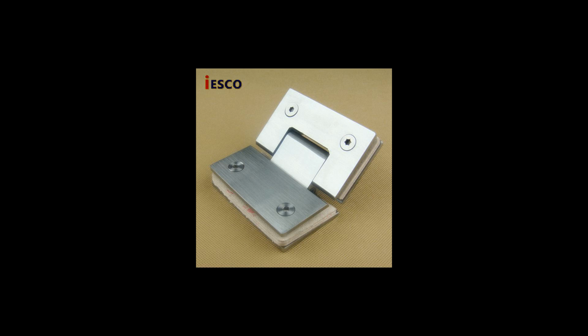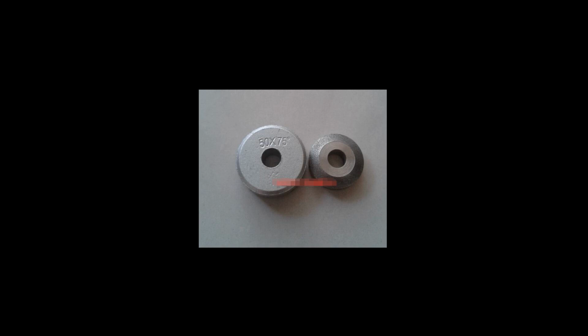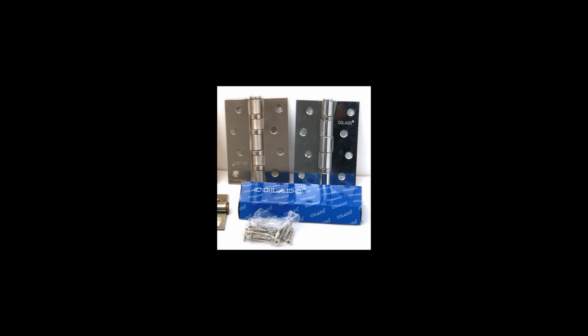A barrel is a component of a hinge that has a hollow cylinder-shaped section where the rotational bearing force is applied to the pivot, and may also have a screw-shaped section for fastening and/or driving the pivot. Pivot hinges, which pivot in openings in the floor and the top of the door frame. Also referred to as a double-acting floor hinge. This type is found in ancient dry stone buildings and rarely in old wooden buildings. These are also called half-hung doors. They are a low-cost alternative for use with lightweight doors.